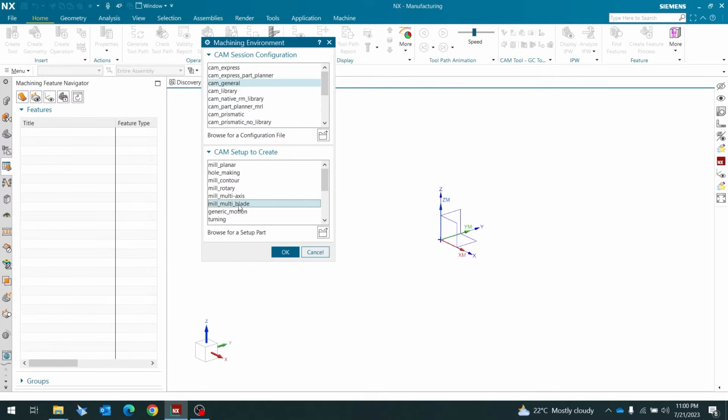So automatically it will generate the operations for a mill planar like structure. There you have to select hub, shroud, and all the different parts of a surface you need to select to generate an operation. So presently I will go for this mill planar. It's not like I have selected mill planar, so I have to do only mill planar operations. Not like that. You can switch to different setups according to your need.